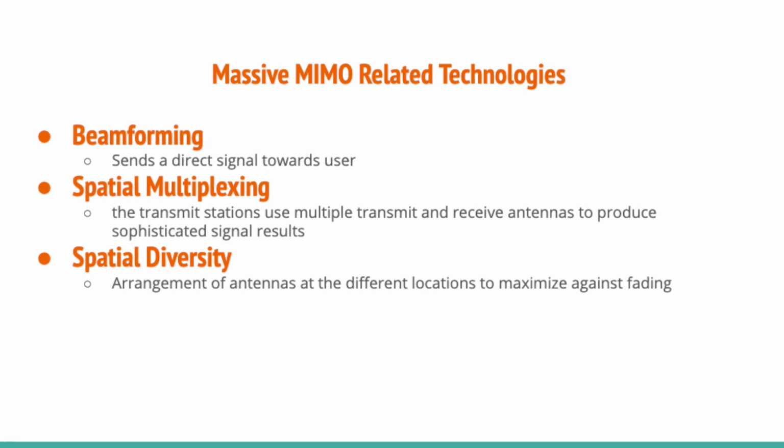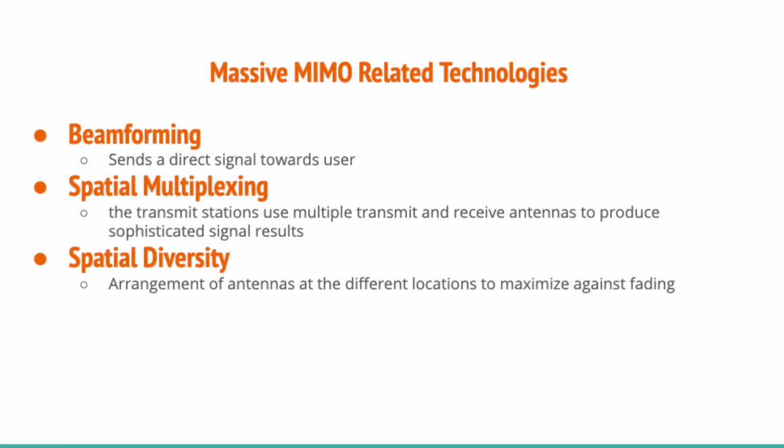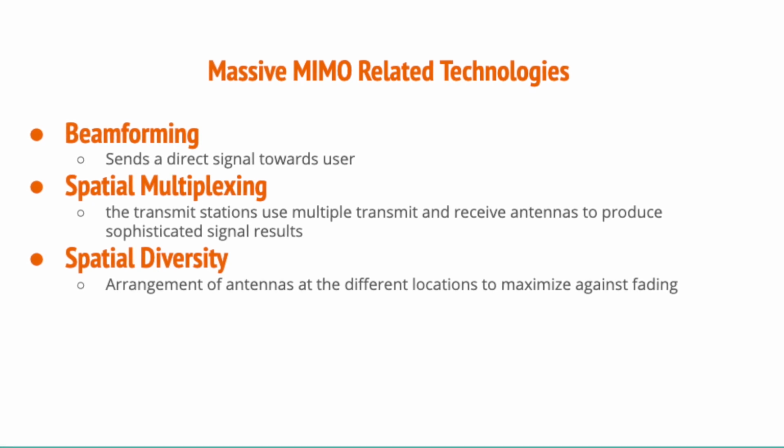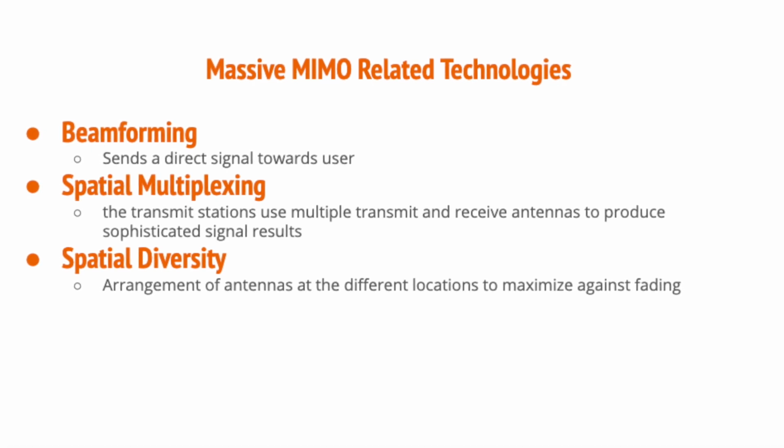In line of sight propagation, beamforming results in a well-defined directional pattern. However, conventional beams are not a good analogy in cellular networks, which are mainly characterized by multipath propagation. When the receiver has multiple antennas, transmit beamforming cannot simultaneously maximize the signal level at all of the receive antennas, and pre-coding with multiple streams is often beneficial. Note that pre-coding requires knowledge of channel state information at the transmitter and the receiver.